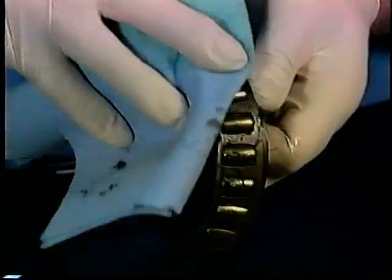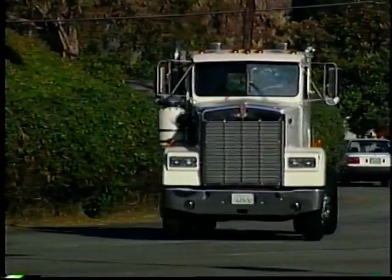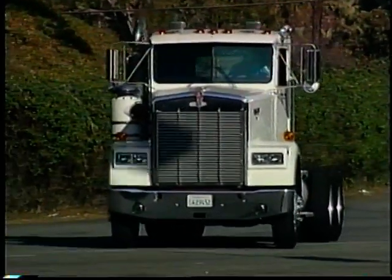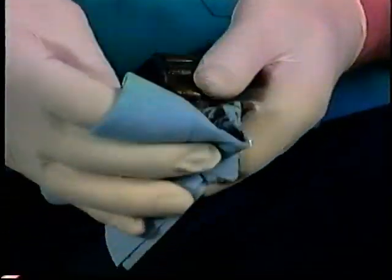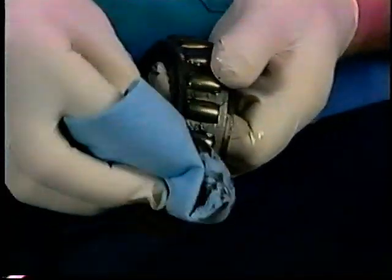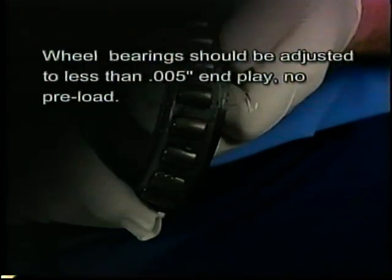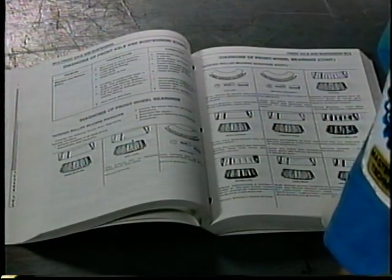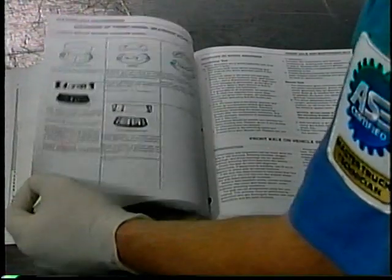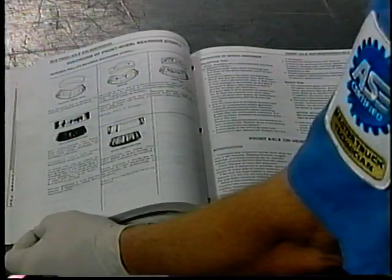Wheel bearing diagnosis is necessary when investigating the cause of vibration or noise problems. Loose wheel bearings will cause loose steering, tire wander, shimmy, and vibrations. Loose bearings should be removed for inspection, cleaned, and then reinstalled. Wheel bearings should be adjusted to less than .005 inches end play, no preload. If there are signs of wear on the bearings or races, consult a wear diagnosis chart to determine the root cause of the problem. Correct the cause, then replace the bearing and races.